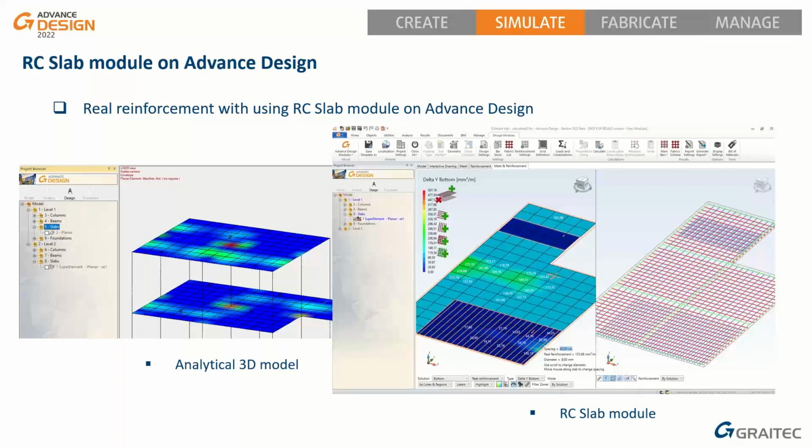We can open a concrete slab with the new RC Slab Module in the Advanced Design environment. If some of you use Revit and our tools for detailing, you know that the slab module exists in the Revit environment. But with this version, we expand it, we provide new options, new workflows, and it works on top of Advanced Design. What is that module for? It allows us to generate the reinforcement based on the theoretical reinforcement, but we can also calculate the theoretical reinforcement using the strip method.